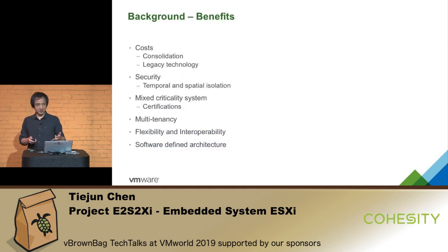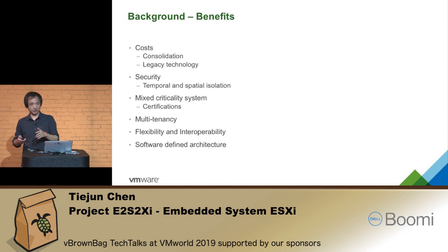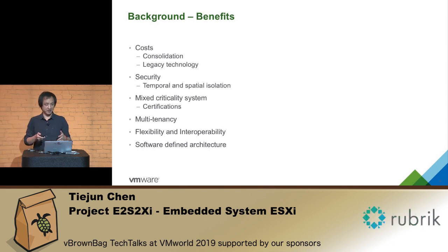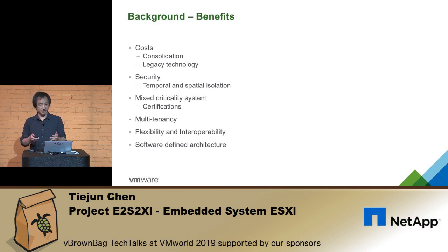Why do we need virtualization on embedded systems? There are some benefits, starting with cost. Typically, we can use one powerful multi-core platform for hardware and software consolidation. Think about it: we can run one general-purpose OS, another instance running an RTOS, a real-time system, and even some legacy operating code, because with IoT, much legacy code must be deployed. But we have a VM, right? This can help us speed up time to market.